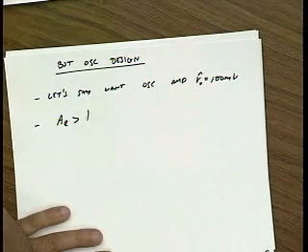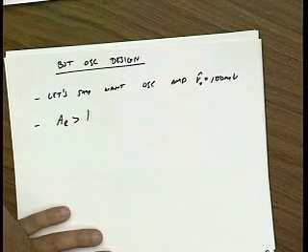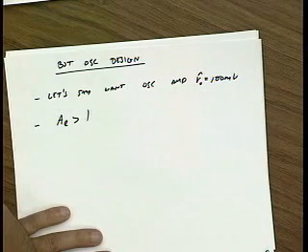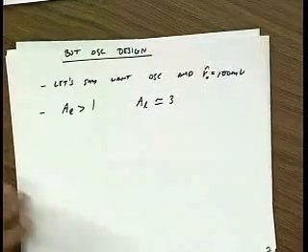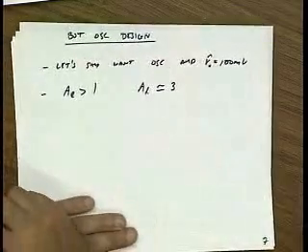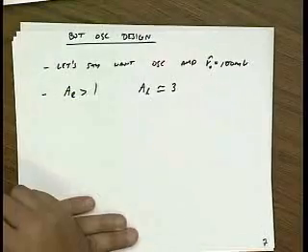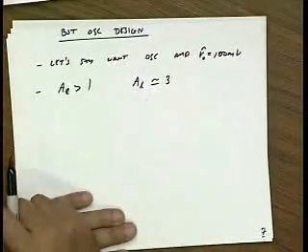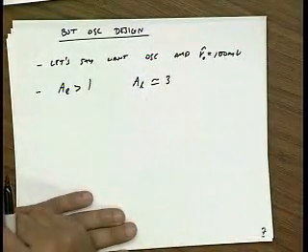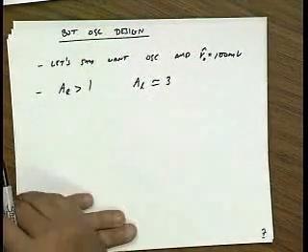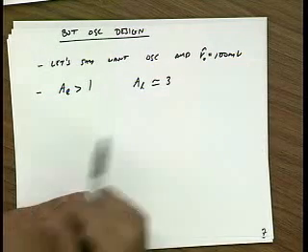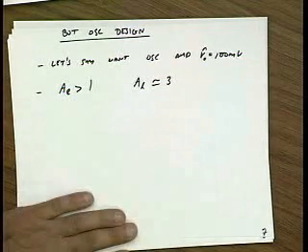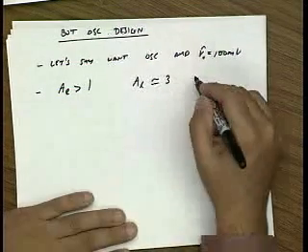So this is where engineering comes in. An engineer says, well, the loop gain has to be bigger than 1 over process, over temperature, over everything. So why not make it, let's say, 3, right? Seems like a very arbitrary choice. But in practice, you could say that 3 leads to a pretty good design. You could think of this as a starting point. I'll choose a loop gain of 3, and then I'll run some simulations and see how the performance changes if I change the initial loop gain. But this is a good starting point.